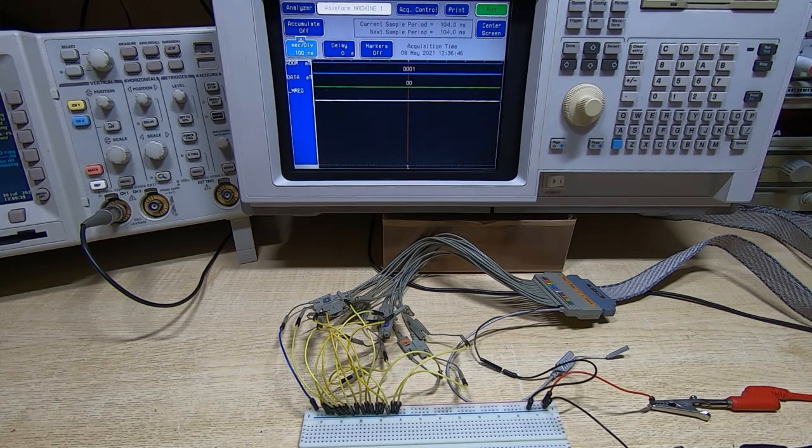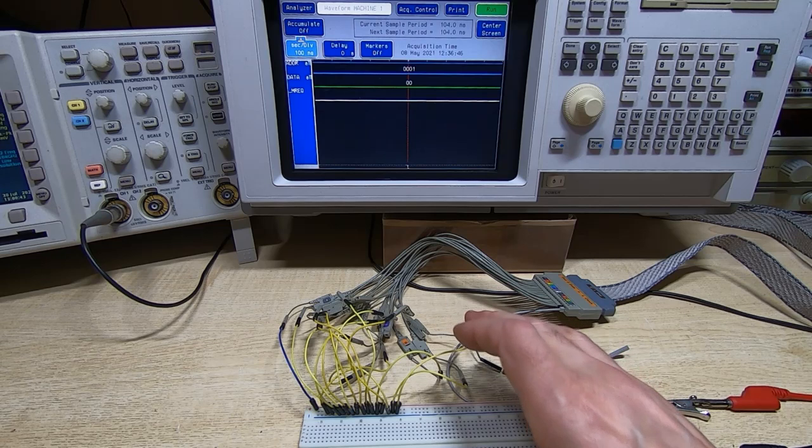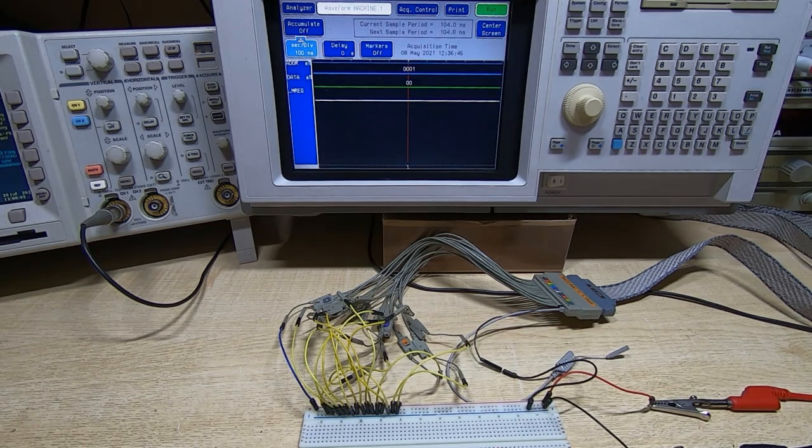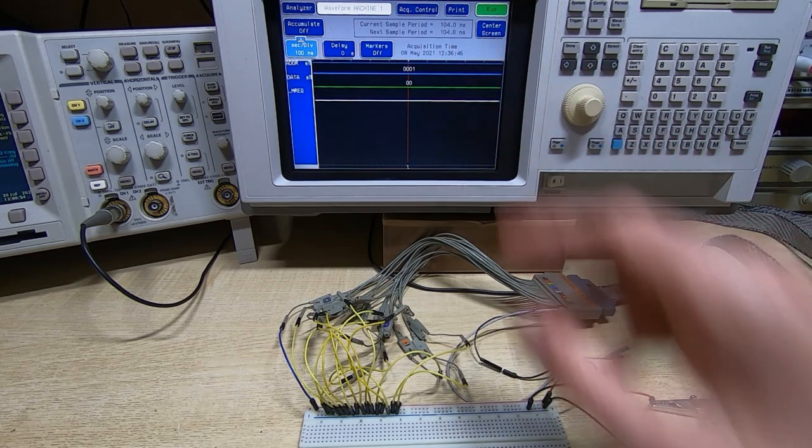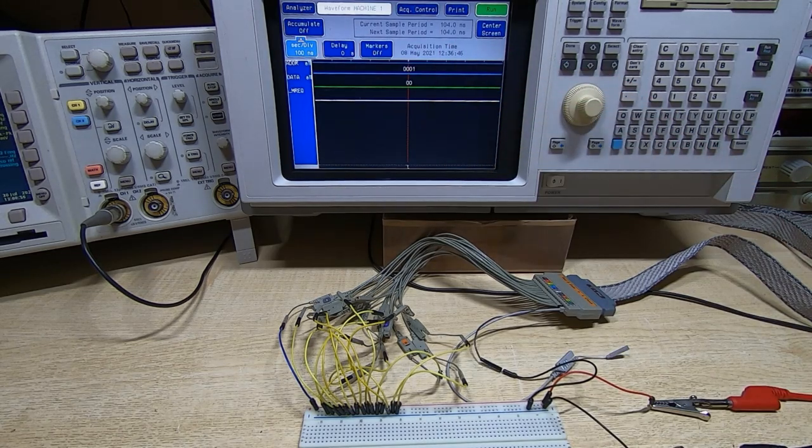Now sometimes you'll be working on machines where the bus is inverted, so a machine like a PDP for example, a 0 voltage on the bus actually represents a binary value of 1, and sometimes you'll want to capture data using that polarity. You're interested in the actual signals, but sometimes it's the actual data values that you're trying to capture or that you're interested in.